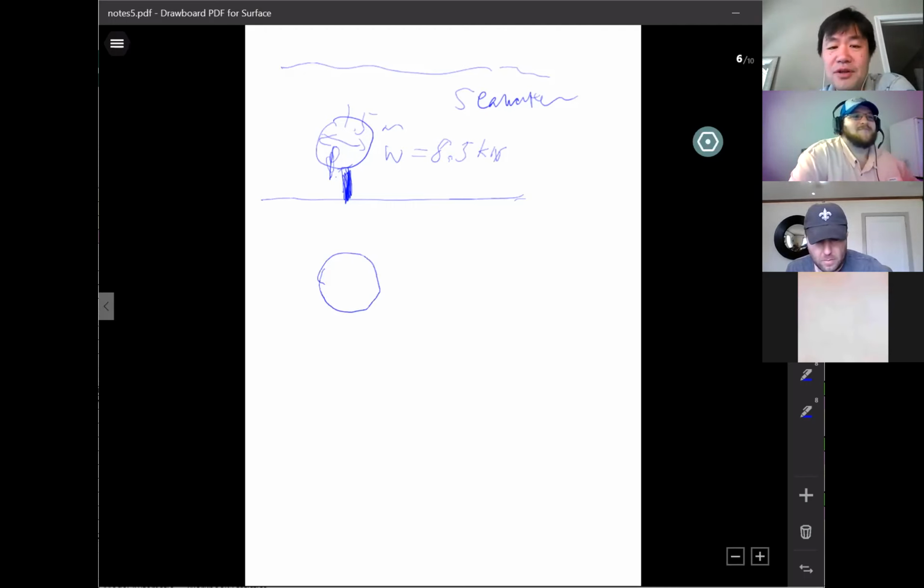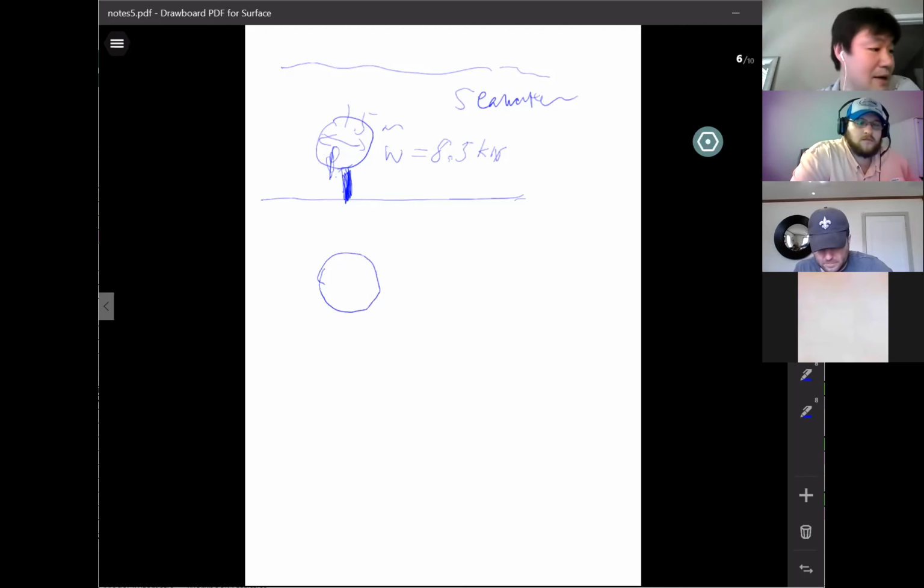I don't know the direction of that supporting force in there. Okay, doesn't matter. If you don't know, put an arbitrary direction. You can put upward or downward, it doesn't matter. If the calculation turns out to be negative, that means your direction is opposite. If it turns out to be a positive value, that means your direction is exactly correct.